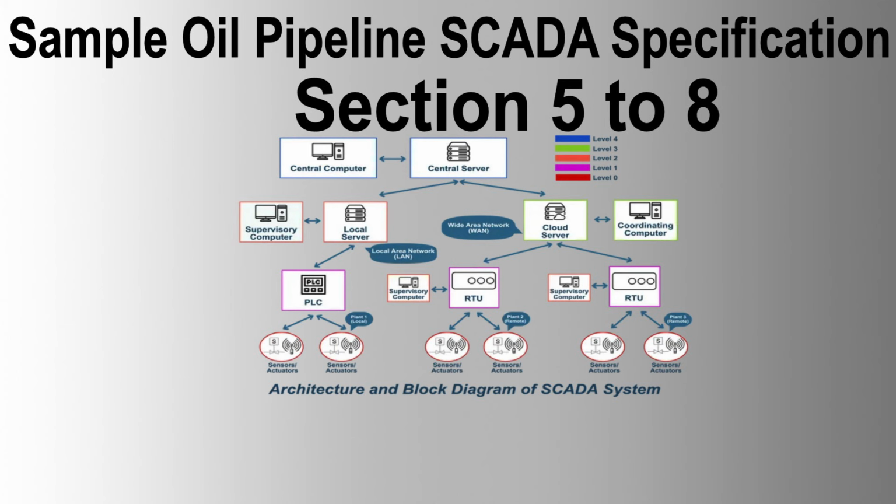6.7.5 Intrinsic Safety. All sensors and solenoids shall be part of certified intrinsically safe circuits with shunt diode safety barriers. Barriers shall meet the requirements of EExia IIA T3 as a minimum. Each barrier shall be identified on the mounting rail by labeling with loop tag number, rail identity, and barrier position number. 6.7.6 Lighting and Power Socket Outlets.